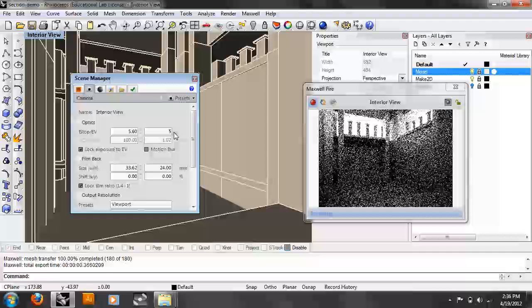Now watch what happens with those windows though, right? They get kind of blown out. That's actually just what happens in a lot of cases. If you take a picture from inside and it's relatively dark and the only light's coming from a small light source, those windows are going to blow out. You won't even see what's outside because all you get is the light because you've left the shutter open, right? This is not a very bright space, but by leaving the shutter open, I gather enough light to actually look at the space, okay? So for your interior renderings, by and large, you're going to have to set a low EV. It's going to be a different EV than your exterior rendering, okay?